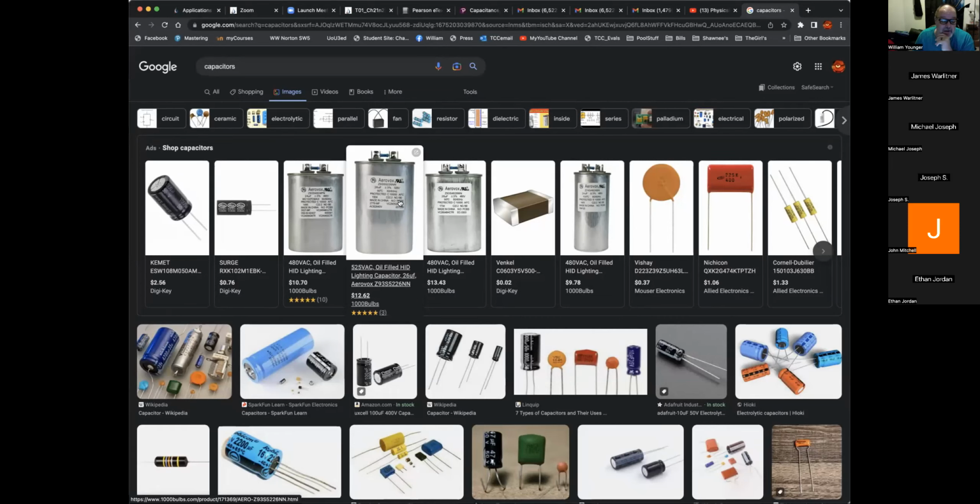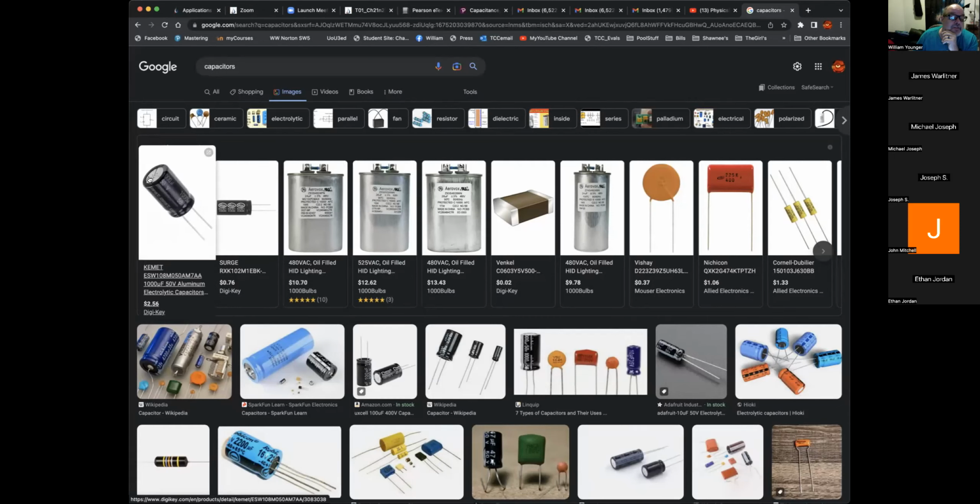And in fact, I've been fortunate enough that just about every time anything electronic I have breaks, I can open it up and almost always find a capacitor, which, notice, has that fancy little Mercedes symbol up there. That breaks right there, and those things pop up, and you see little triangles stuck up. Or sometimes you'll see they're so bad that the whole thing's swelled up. A lot of times when something electronic goes bad, it's a capacitor that died.